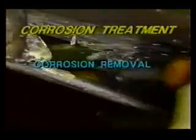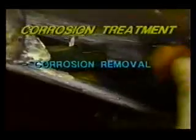Once the paint and stripper are removed, you can begin repairing the damage that corrosion has caused. First, you must remove all of the corrosion product and damaged metal. The corrosion removal procedure will be different for each metal or component, but this video will provide you with a good working foundation. Refer to AC 43-4A for material or component specifics.